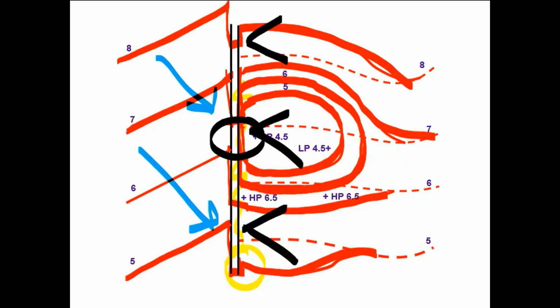This is very important for you to understand before you go forward. One of the things that I often do is trace these contours in different colors and leave a little bit of space right behind the curb where I let those contours stack up, just so I can see them right now and I don't forget where they're located.